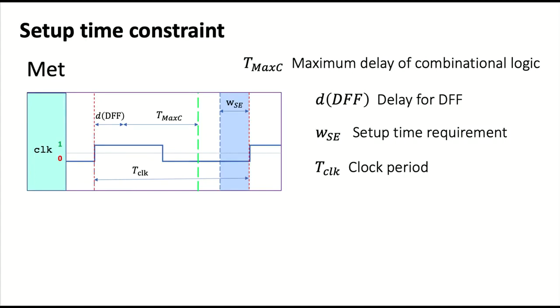That's called the propagation delay, or the response delay, of the flip-flop. The flip-flop doesn't immediately change the output. So the first thing that happens after the clock edge is that after a certain amount of time, again a property of the flip-flop, the output will change, or may change. Maybe it's loading the same value it already has. But if it does change, it will take a certain amount of time before it assumes a new value.